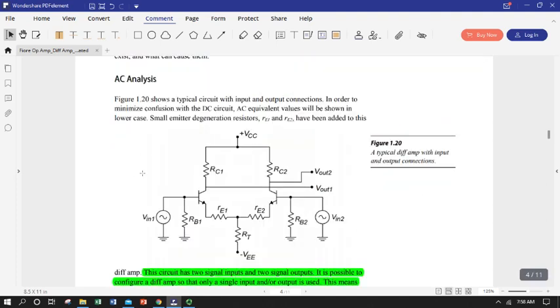Okay, so let's get into our AC analysis. And for this, unfortunately, Mr. Fiore kind of broke his rules. He's not modeling his BJTs the way we would probably want to see. He's leaving the schematic. These should really be those AC current sources right here, because a good AC model of a BJT would just be an AC current source in the direction of conventional current flow instead of the schematic symbol, but he's kind of left the schematics in.